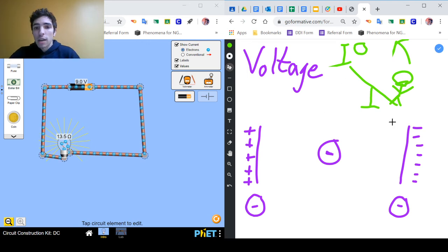And so again, our analog to voltage, because I'm trying not to get on a seesaw tangent here, is that if we need more energy, or we needed our electrons to move even quicker through our circuit, if we wanted more current, then we could increase the voltage by increasing the number of charges on these two plates, or by decreasing the distance between these two plates. But those are the ways that we can control basically how high up we drop this ball from, or how we would give this electron more energy.